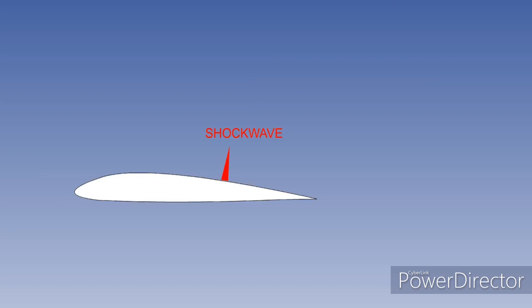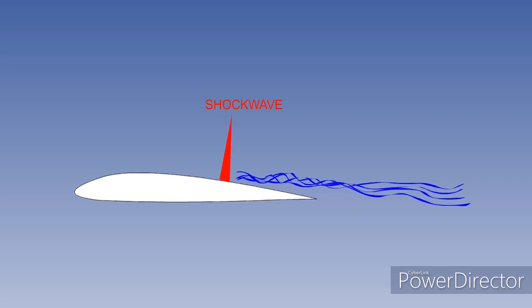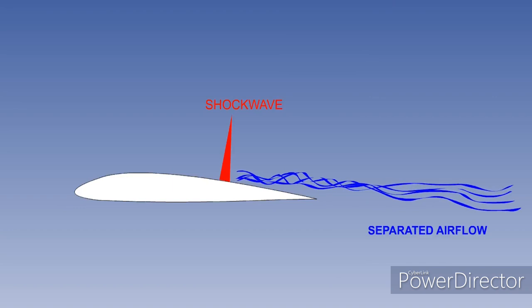At high altitude, a large high-speed jet transport will be cruising at a speed marginally above its critical Mach number, and will have a small shock wave on the wing. If the aircraft's speed is increased, the shock wave will rapidly grow larger, causing the static pressure to increase sharply in the vicinity of the shock wave. The locally increased adverse pressure gradient will cause the boundary layer to separate immediately behind the shock wave. This is called a shock stall.